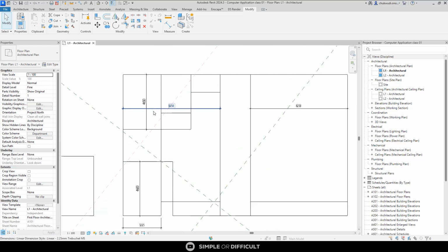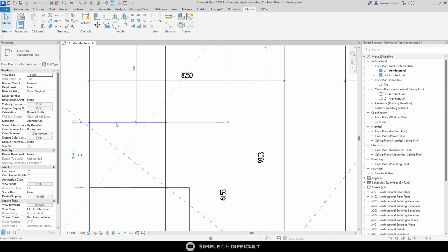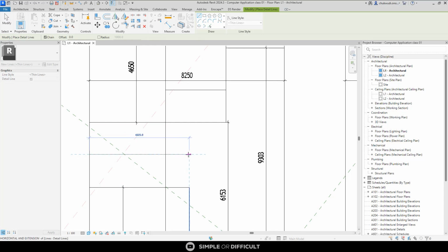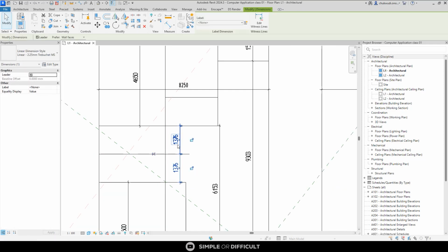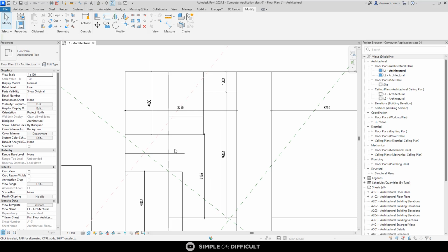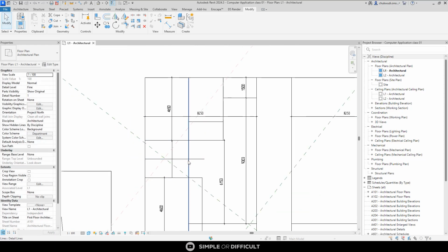Now, these 2 bedrooms are going to have a bathroom. Let's handle that right away. So to add a toilet, I'm just going to use CS to draw a line here and make sure it's in the middle of this space right here. I'm now going to delete that dimension. I'm going to select the offset tool and type in 2000, and offset it like so.